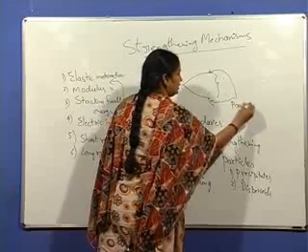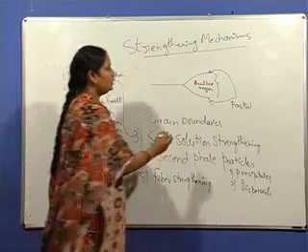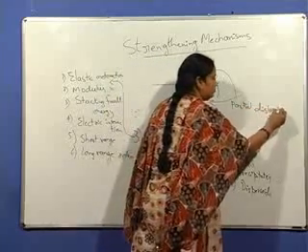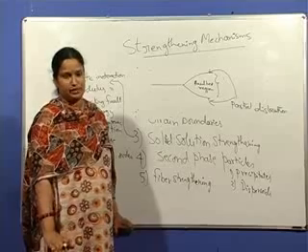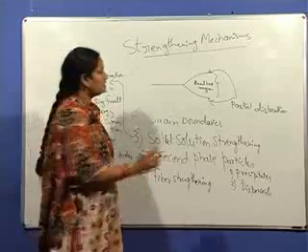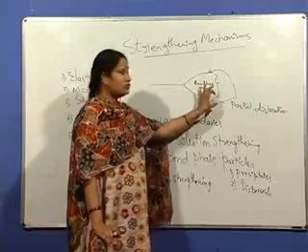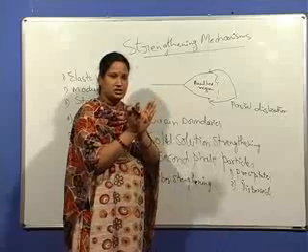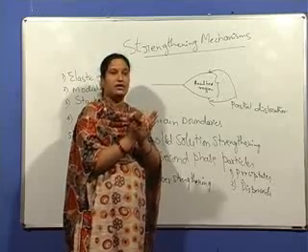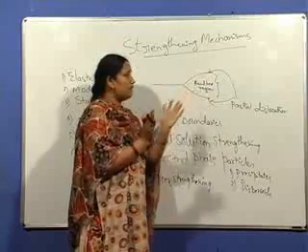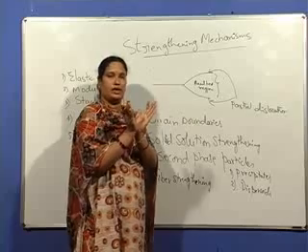Between the partial dislocations there is a faulted region, surrounded by the two partial dislocations. This stacking fault is associated with some energy that is known as stacking fault energy. The higher the stacking fault energy, the lesser is the separation between the partials, so lesser is the faulted region, and these two partial dislocations try to come closer together. The lower the stacking fault energy, the greater is the faulted region, and these two partial dislocations move away from each other.